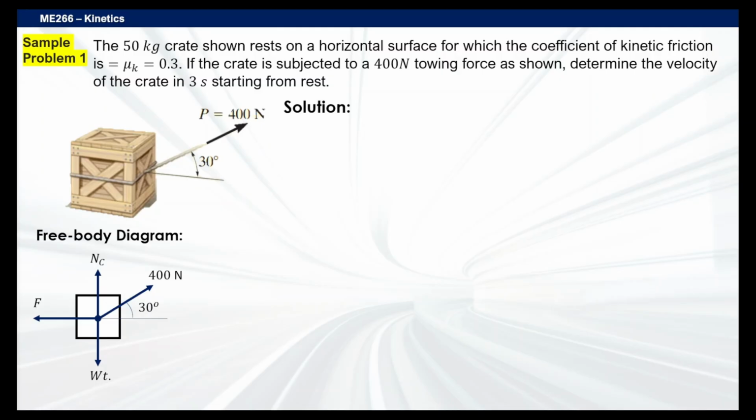And then next up, we don't know the perpendicular force, and we don't know the acceleration here. So we need another equation to solve it. Luckily, we have the y forces. So the summation of forces on the y-axis equals mass times a sub y. In this case, do we have an acceleration on the vertical axis? No, the short answer is no, because it's only moving on the horizontal plane. It's not levitating, it's not moving up, it's not a projectile. So it's basically 0 here.